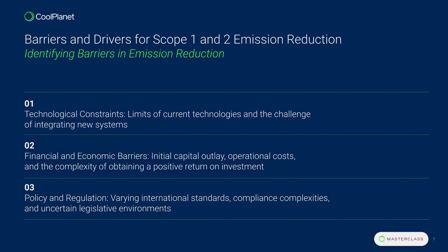I suppose, as I was referring to previously around steam heat pumps, while they're not available in a smaller, just say a commercial or light industrial state, there is mechanical vapor recompression technology. Yes. There is the opportunity to generate steam through electricity at maybe a larger or a heavy industrial scale. Yeah.